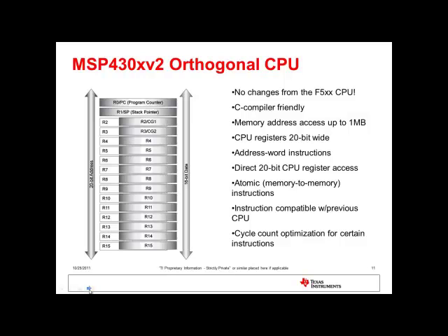The MSP430X RISC CPU includes features such as an orthogonal architecture, full register access including program counter, status register, and stack pointer, single cycle register operations, large register file that reduces fetches to memory, a 20-bit address bus that allows direct access and branching throughout the entire memory range without paging, a 16-bit data bus that allows direct manipulation of word-wide arguments, a constant generator that provides 6 of the most often used immediate values and thereby reduces code size, direct memory-to-memory transfers without intermediate register holding, and byte, word, and 20-bit addressing.